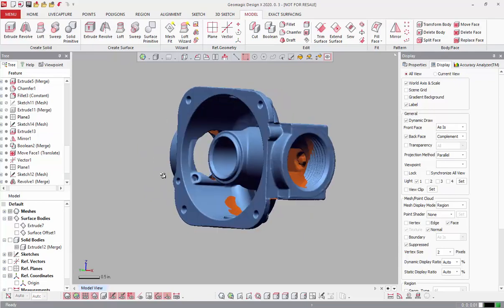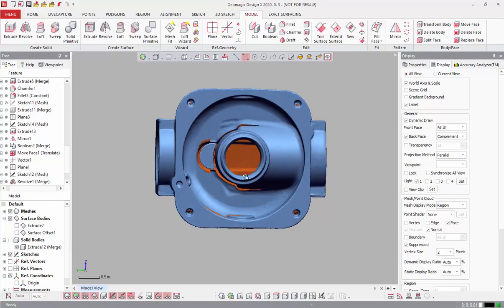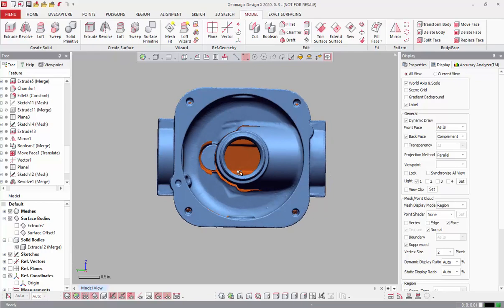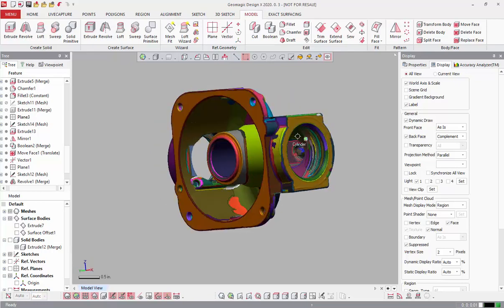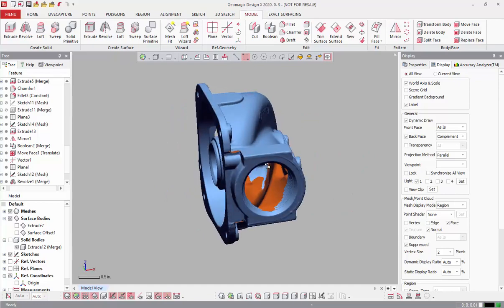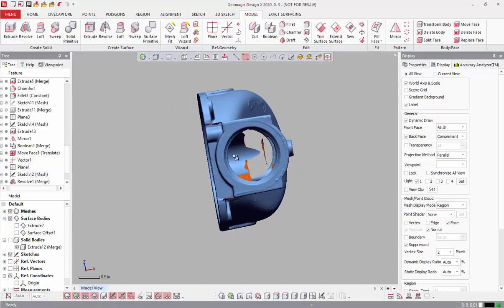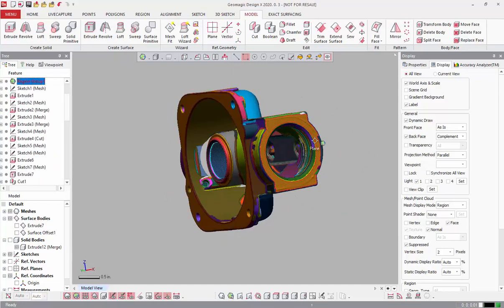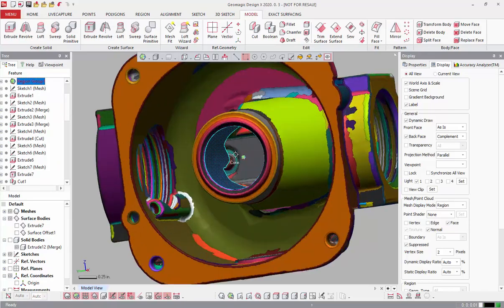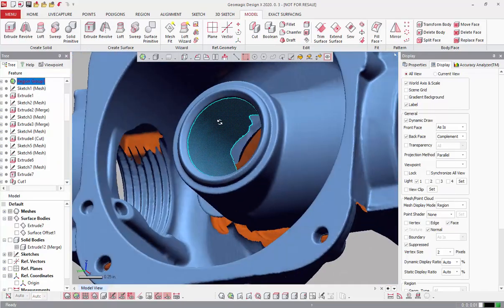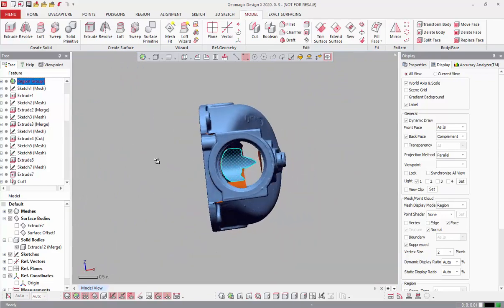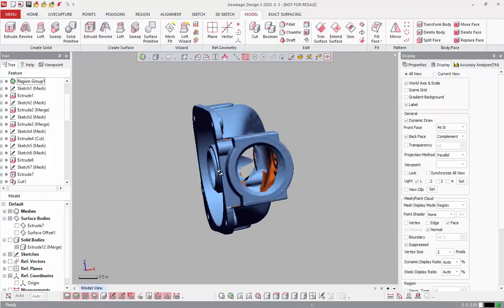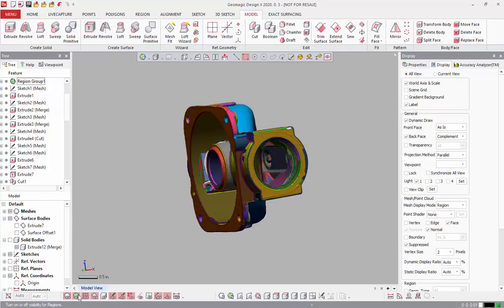Looking at this part, it looks like this interior hole blends in fairly well within it. This is a smaller diameter hole, and the software actually says it's a cone rather than a cylinder, so it looks like it tapers a little bit as it blends in with the longitudinal hole here. So let's work on those first, and with that, we get to start talking about helixes and doing threads.